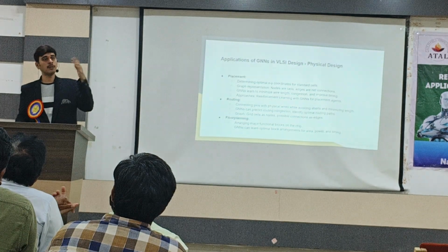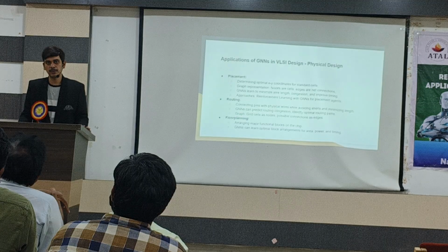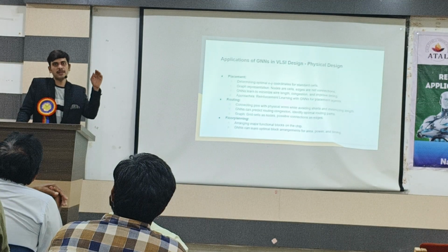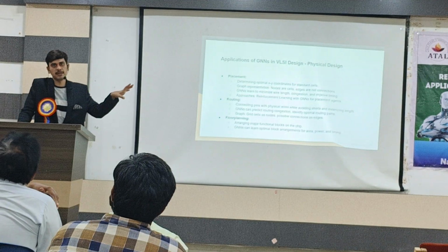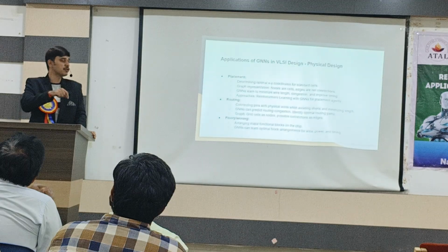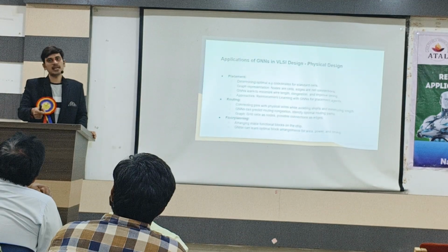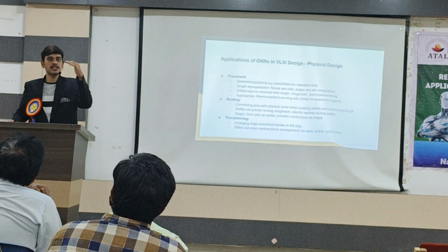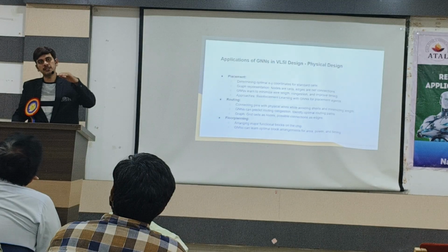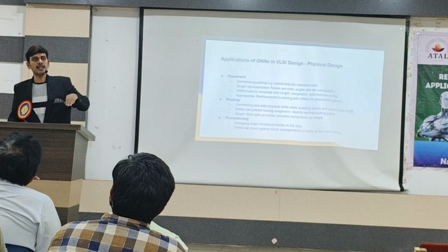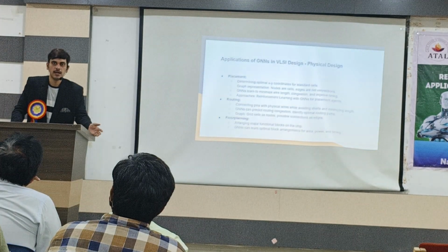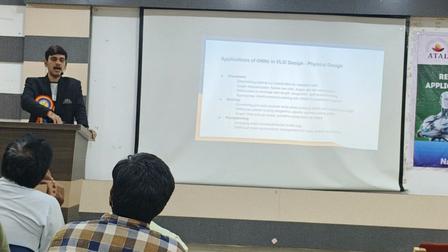So if we have an abnormal uncertainty, that's a library setup issue. These limits will come from the library, so we have to fix the issue from the library. Based on the particular issues, we have to decide what's causing the timing violations. Initially, these are all constraint-related things we have to close, and then we have to do the feedback with the PNR.